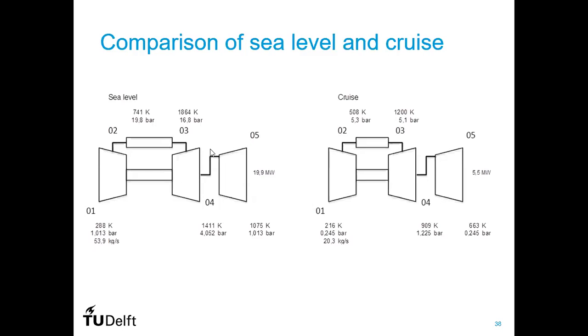You don't have a separate engine for takeoff and cruise. With the same engine, you have quite a high life consumption during takeoff, but it's a short period, and a low life consumption during cruise, but that's a long period. So there's a good balance. But it's important to know, it's also linked to the next class. This is really important. This inlet temperature is an important parameter that determines the performance of your cycle and also determines the life of your gas turbine.